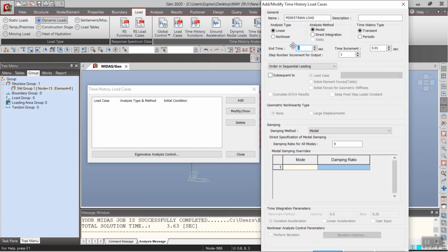multiplying it by 0.508, which is the period of the loads, you will have 6.604. So to consider the vibration due to the final loading, I should have an end time longer than 6.604 seconds. So that means, let's say, 8 seconds.